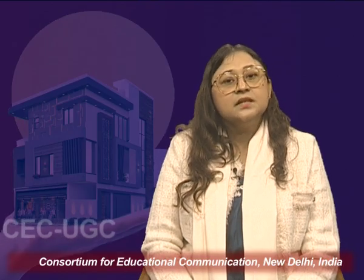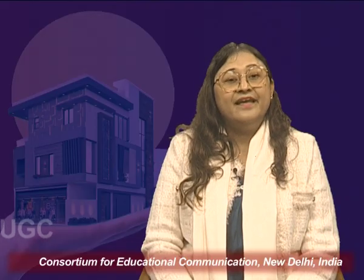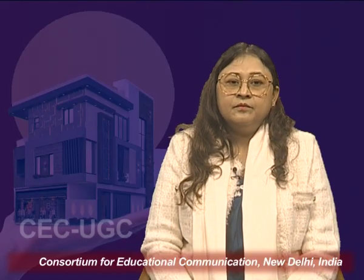In airport vicinity, the height is fixed in consultation with the civil authority. So, the areas which fall nearby the aviation aerodromes and airports will have again a curtailed restriction of height. So, this will be around 15 meters for Delhi NCR, and different from somewhere else depending upon the bylaws, but in India as per the model building bylaws it is 15 meters, adherence is important.